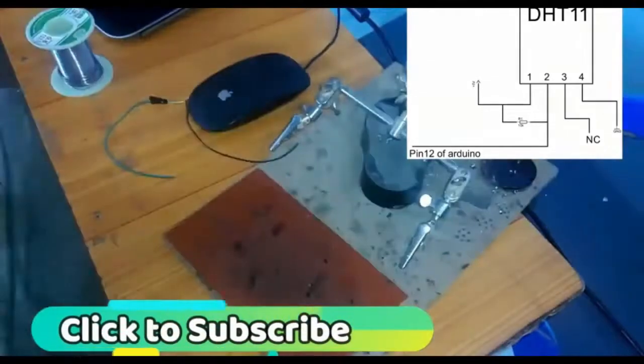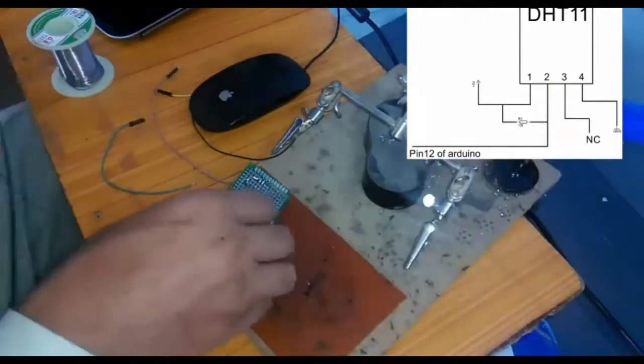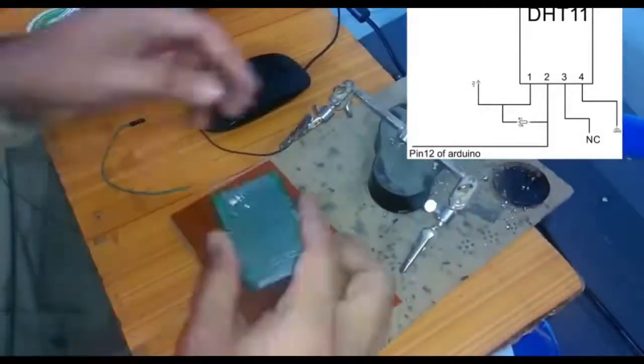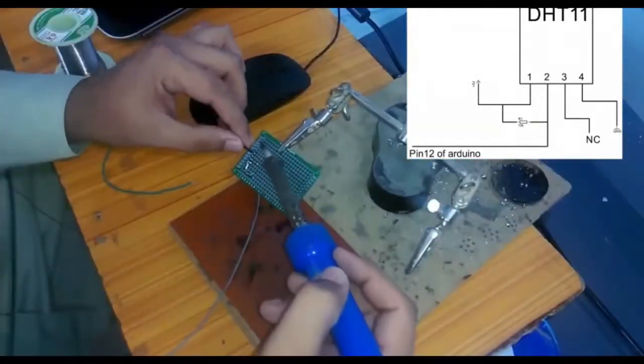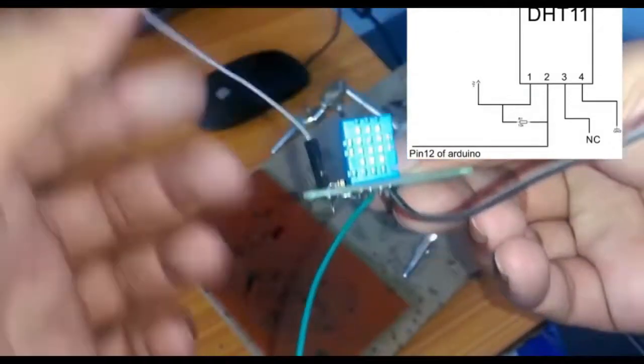Now it's time to solder the wires. This is the 5 volt wire which is connected with pin number 1 and one side of the 10k resistor, and this is the ground wire on pin number 4, and the green wire is on pin number 2. So all the wires are soldered.